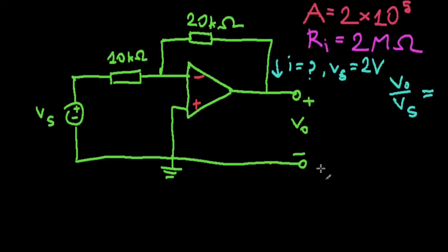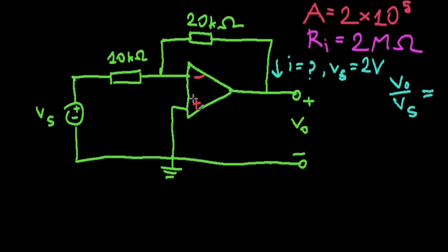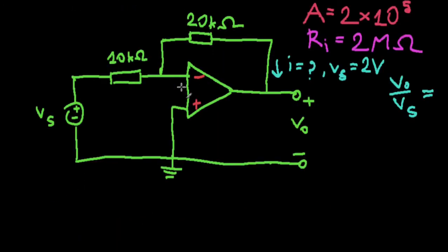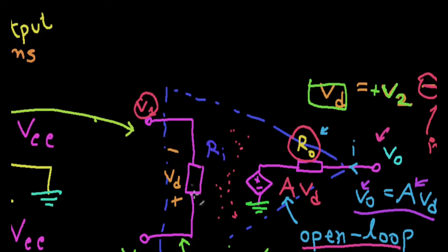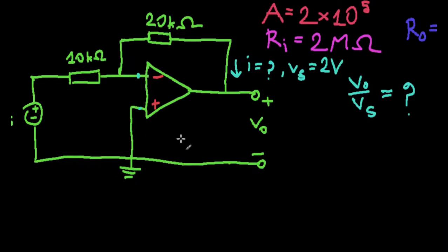As you can see, we just replaced the op amp. This is going to have two parts to it. These were my input terminals, right? All I did was, as we saw in this diagram, we just put the equivalent circuit: from this end, it's just your input resistance, this large resistance connected to your two inputs. I just put that resistance between those two input terminals.